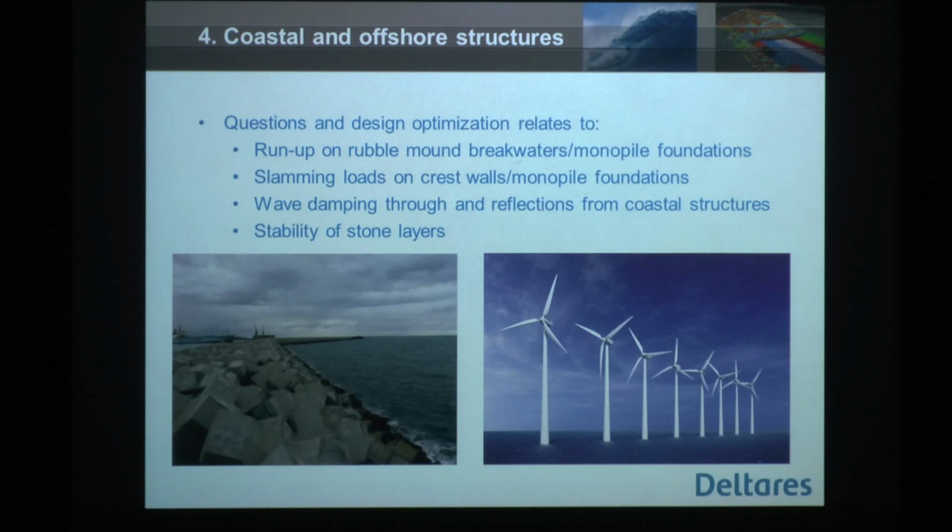So we want to have either waves reflected or the wave energy dissipated through the breakwater, so we have sufficiently quiet water on the other side so we can have safe loading and unloading of ships in the harbor. And then of course also stability of stone layers, both when it comes to breakwaters but also scour protection around any type of coastal and offshore structure.